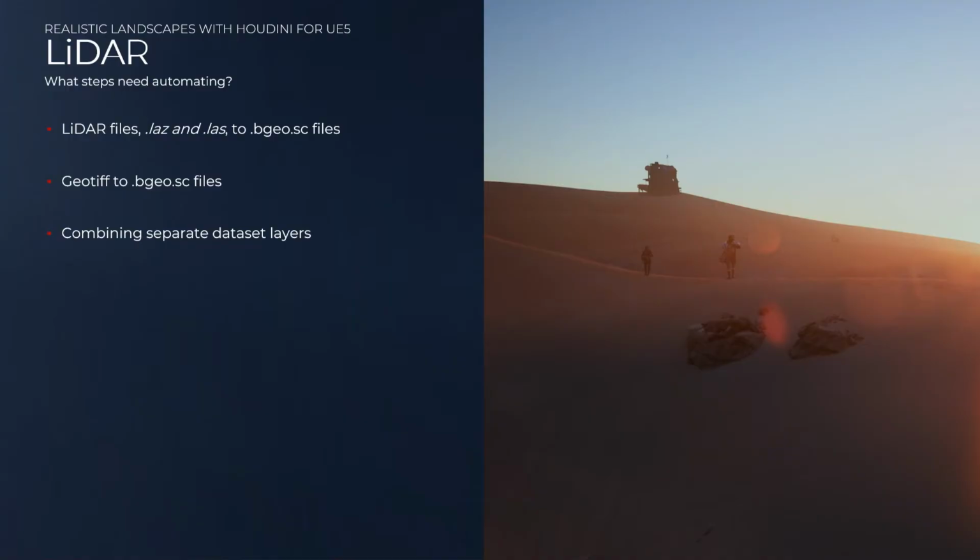Maybe you find a high elevation data set at some place, and then you find a nice imagery data set from another place. Those need to be aligned, and their map projection needs to be matched, and you need an output. So I've started to use QGIS as an intermediate step, where I can script QGIS, read in those data sets, get them to match up, and then export the extent with the same projection model.